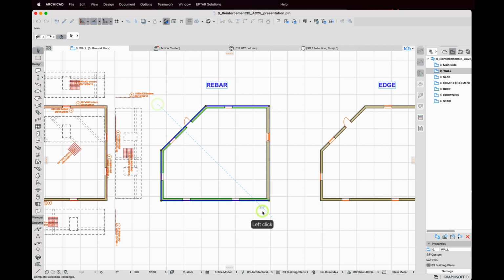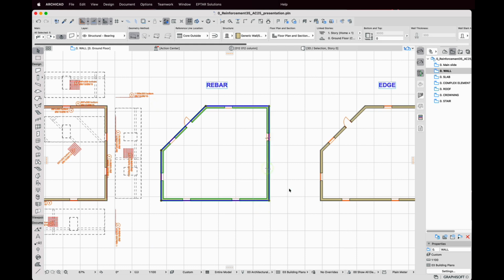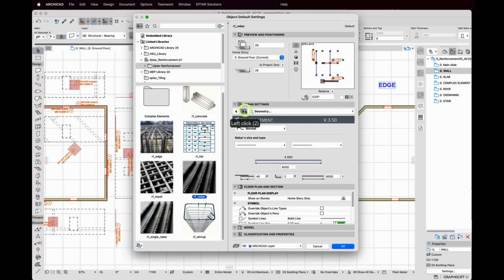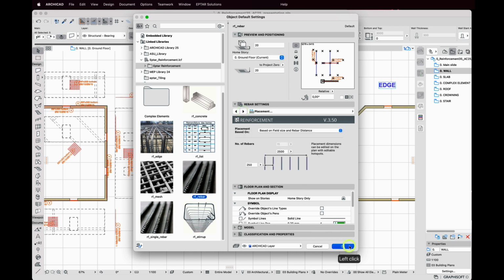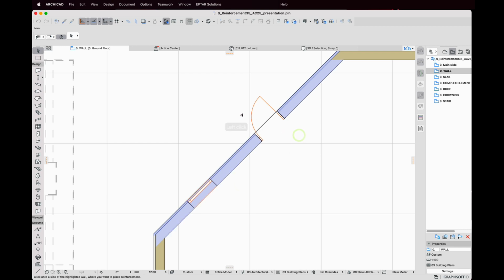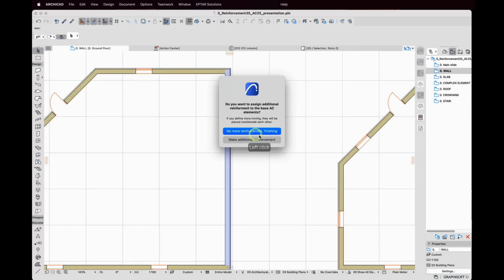The rebar works like the mesh. I select all walls where I want it placed. Click on the wall tool in the reinforcement palette and set the position of the rebars. This is important because in the wall it can only be vertical or lateral. I select vertical. On the next tabs, I set all other parameters, like the shape of the rebars, and click on OK. Like in the case of the mesh, the eye cursor appears. I select the necessary side of the wall and click.